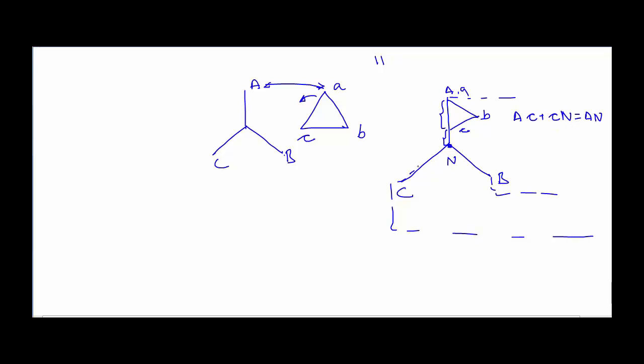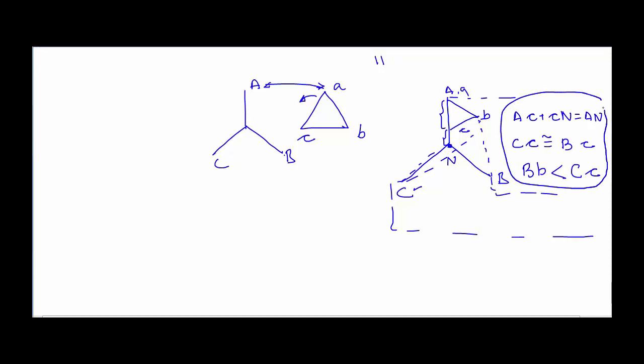Then capital C and small c and capital B and small b will be almost equal, so capital C and small c is approximately equal to capital B and small b. And capital B and small c will be smaller than capital C and small b, because the vector length here is longer compared to this one. So this is the pattern of results that we will get if the vector of the transformer is Y and d11.